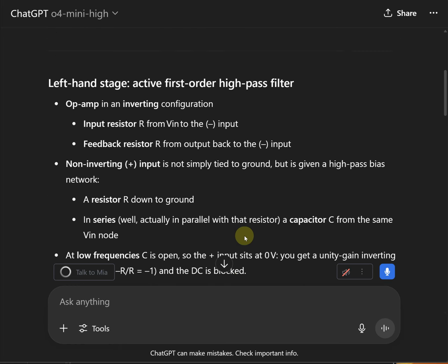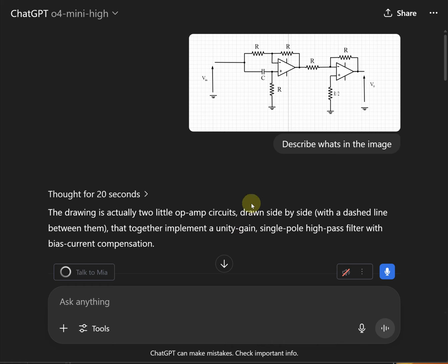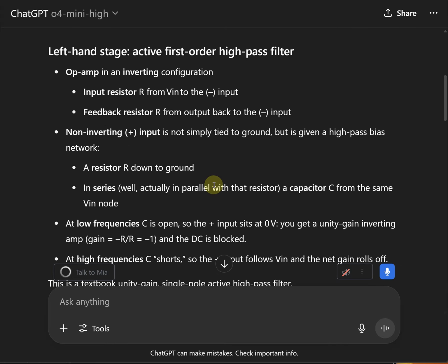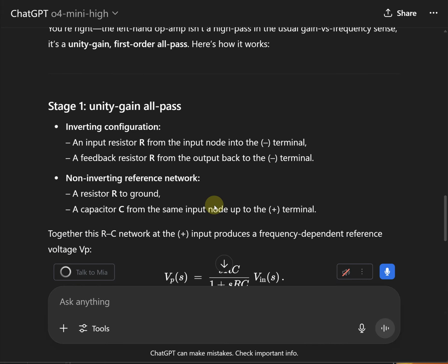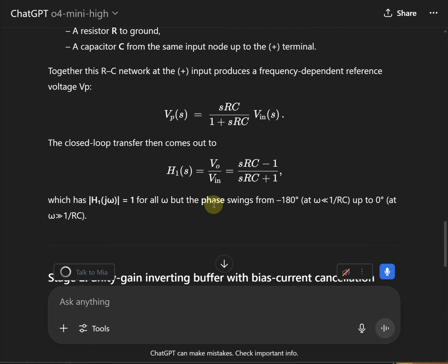It's something you might put on an exam paper for students to be able to work out. One way you can do it is with the superposition principle, by splitting it here and grounding each input one by one, and taking each input in turn. So you can ground this point here, then take the input to there, and then ground that point, and then put the input in the capacitor and work the output out, and then sum them. That's one way to do a solution. There are other ways, of course. So anyway, it's still getting that wrong, but it's getting that bit right.